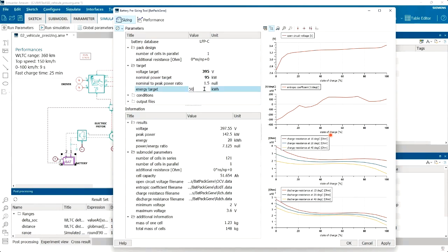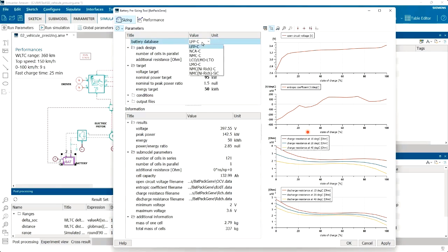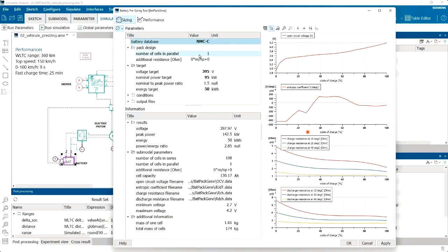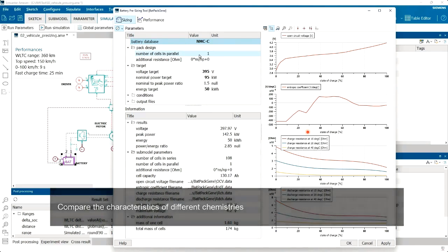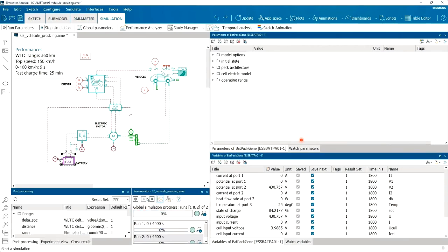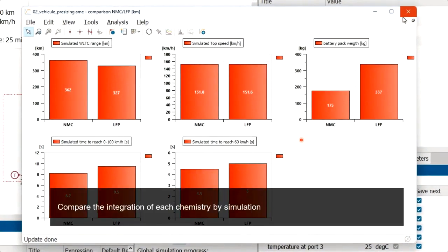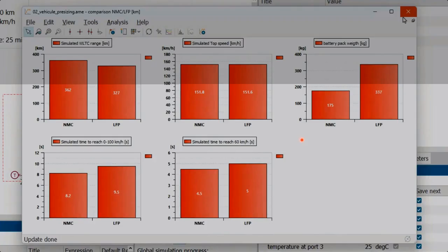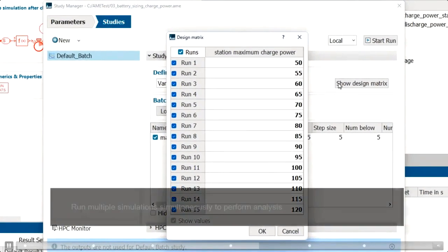So you can define a battery and see if it meets the requirements. There is a database in here within AimSim that you can leverage as well for the materials and compare different characteristics of different chemistries. So you can try those out. This is a way you can understand what type of requirements you need for a battery pack. And then you can start designing the cell in a more detailed geometric manner in BDS, and then bring that cell into 3D in SimCenter Star CCM+.